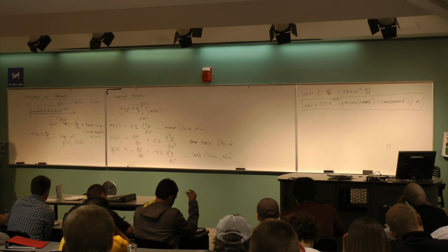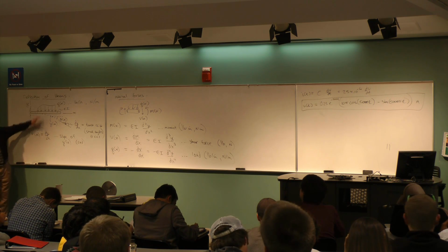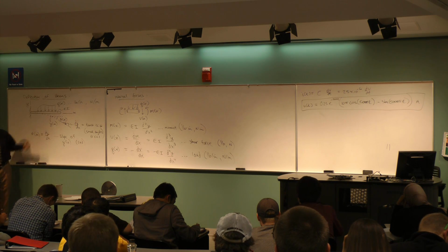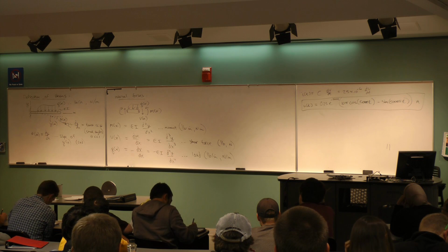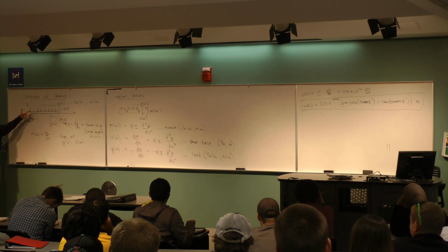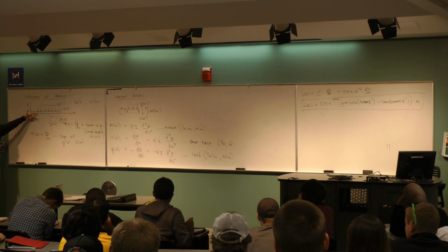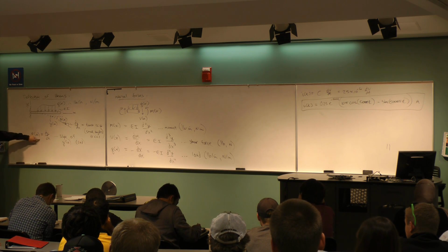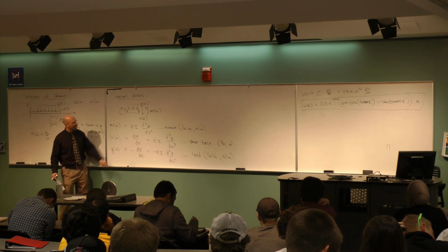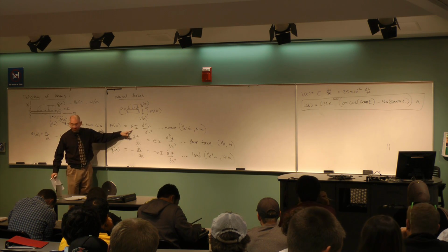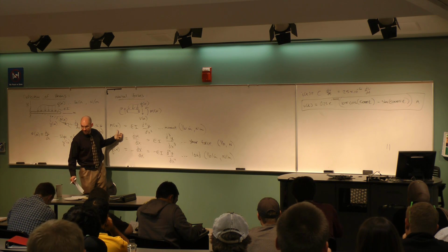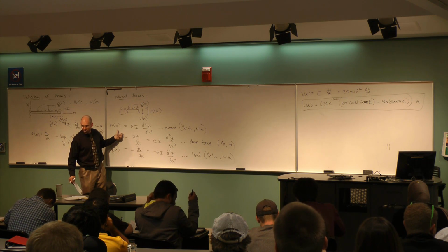Okay, and so what's the punchline to all of this? For a beam deformation problem, if I have an equation for the elastic curve, which in this class we're just going to give you the equation, then if I just start taking derivatives, I can understand everything I want to know about how the beam deforms, and also whether or not it might break, right? Because one derivative gives me the slope, helps me sketch the deformation. Another derivative, multiplied by this EI here, gives me the moment. And it also tells me something about the shape of the deformation.